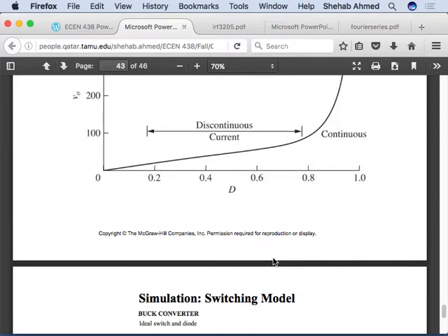How do you deal with that? You have to change duty cycle. How do you change duty cycle? Do you change it very fast? Change it very slow? It will depend on your load, obviously. If your load is a memory, or your load is a processor, processors are operating at gigahertz speed. You buy a 3.5 or 3.2 gigahertz processor. What does that mean? It means that the instructions inside are happening at the speed of 3.2 gigahertz. Each instruction is happening at that speed, which means that the load is changing. Well, what is an instruction? You have different gates inside the processor, which are basically a bunch of MOSFETs.